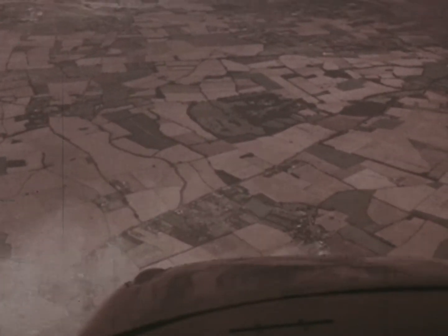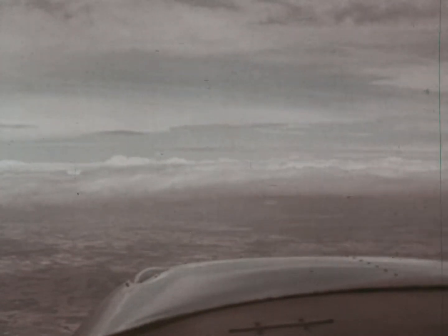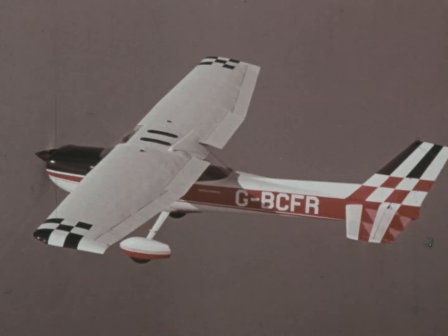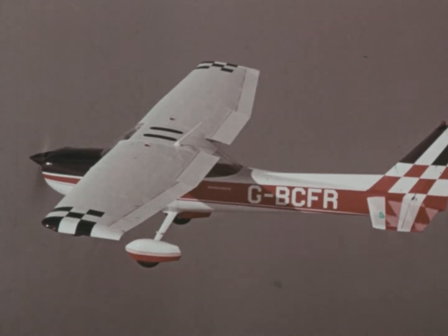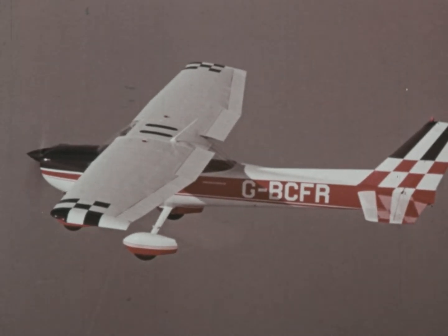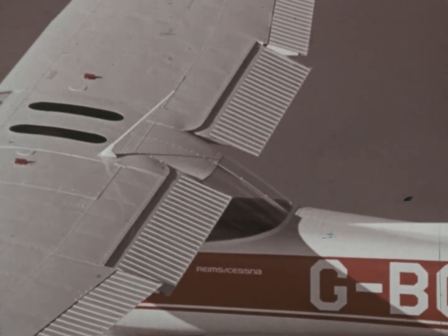The speed at which the airplane stalls will depend on its weight and will increase with altitude as the air becomes less dense. Nevertheless, we must be able to fly slowly, and in particular to land slowly. To achieve this, we can change the characteristics of the wing by fitting trailing edge flaps. These flaps slide out from the wing and curve downward as they do so.